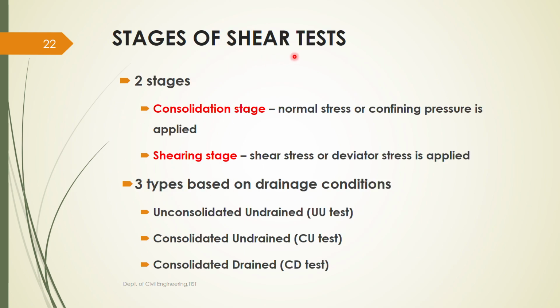See, the shear tests are conducted in two stages. First stage is consolidation stage and second stage is shear stage. What do you mean by consolidation? We have studied that soil consists of soil solids, air and water, isn't it? So if you take a soil and apply compressive load, which component will be escaping first? Air will be removed first, and when compressive load is applied, air is removed and the volume of the soil is reduced.